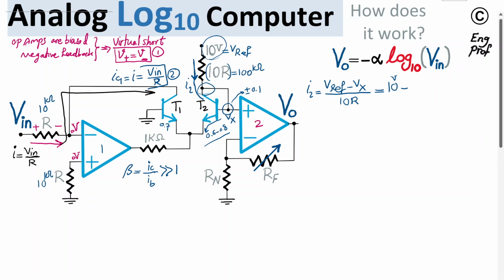So it's changing in that ballpark, nearly 0. With the proper selection of Vref at 10 volt, which is nearly 100 times what is expected to be the variation of the voltage at the base of transistor T2, we can make the assumption that, since Vref is much greater than Vx, on the order of 100 times, this equation is roughly equal to just Vref divided by 10R, which in this case is 10 volt divided by 10R.